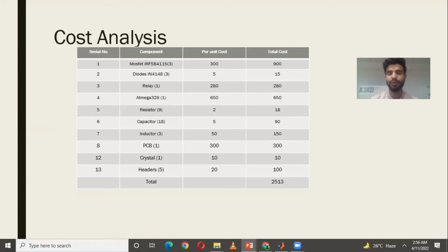If we give input from wind instead of PV, relay 2 will become active. And if we give input at the dedicated third input, it could be a battery or any other DC source, the relay 3 will become active and the other two relays will not become active. This is a 4 channel relay.